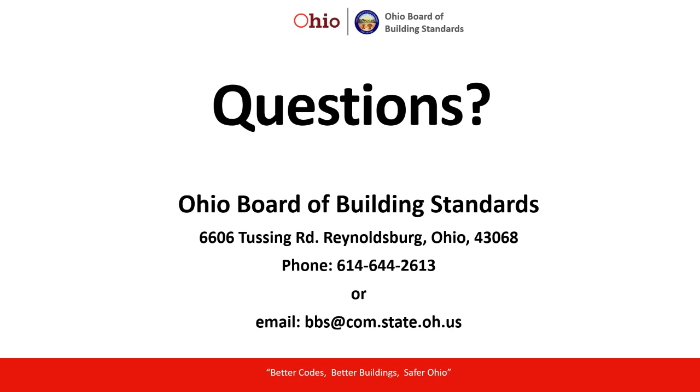Basically, all of the requirements for a traditional single-family dwelling apply to the tiny home. And if you can get the tiny home to meet those requirements, fine. You may not be able to do it because of space constraints, and those will generate a non-compliance issue in plan review from the building official, and that can become an adjudication order that the owner can then appeal and ask for a variance to those conditions. Building officials cannot issue variances. That has to go through an appeals process.